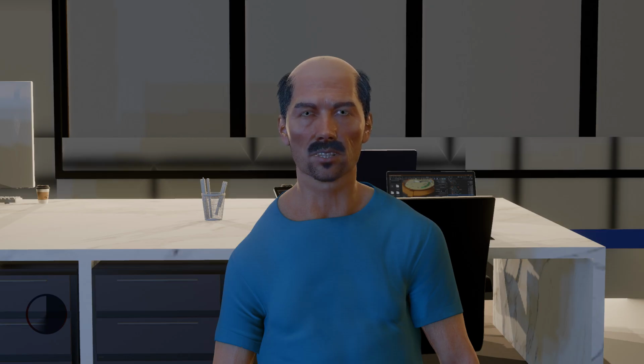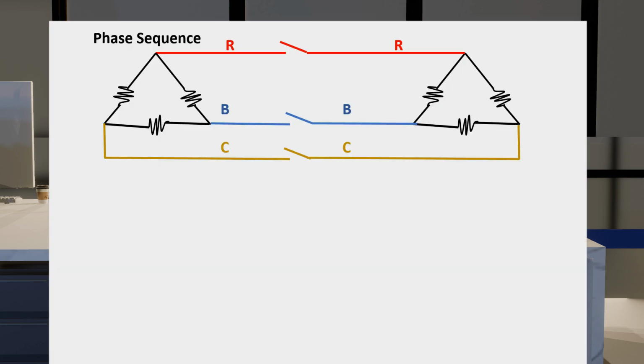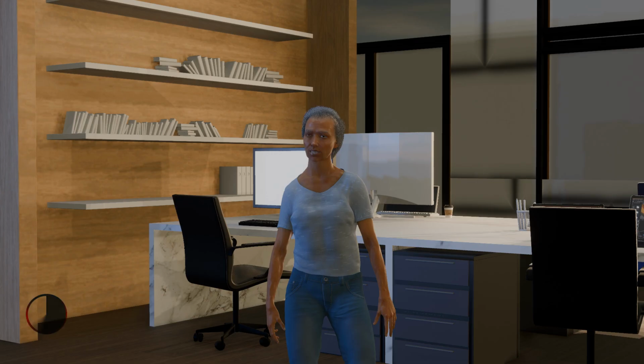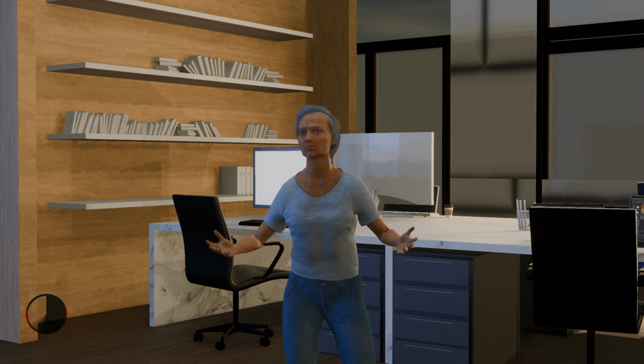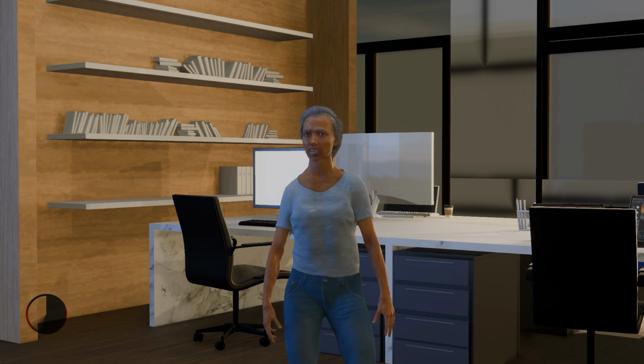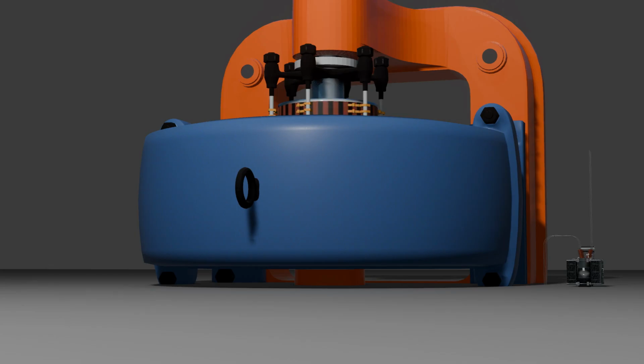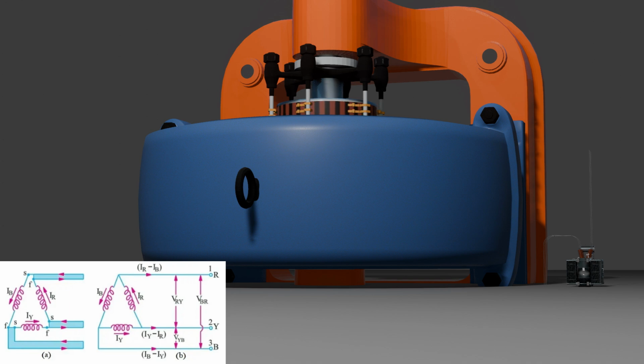Now that we have known the intricacies of frequency, the other conditions are the phase sequence, phase angle, and waveform. Waveform and phase sequence are fixed by the construction of the generator and its connections to the system. During installation, careful checks are made to ensure the generator terminals are connected correctly so that the order of phases matches the system. Connecting a generator with the wrong phase sequence will completely damage the generator or other generators already connected to the system, because the system voltages are opposite to those of the generator terminal voltages.